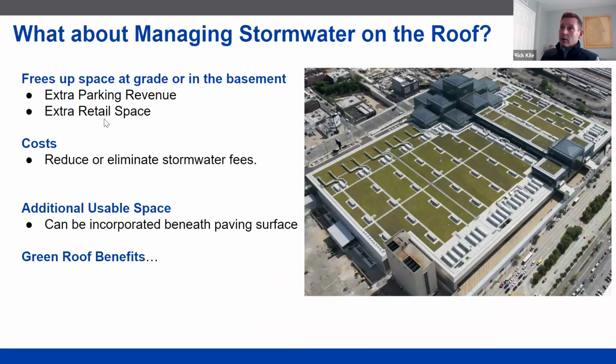But what about managing stormwater on the rooftop? So by moving the stormwater management to the rooftop, we free up space at grade or in the basement that could be used for parking revenue or perhaps retail space. Costs, perhaps in the municipality you're working in, stormwater management objectives can be waived, but there is maybe then a fee incurred to do so. So by managing it still on the structure with other constraints, we are potentially eliminating those fees. And then creating additional usable space.